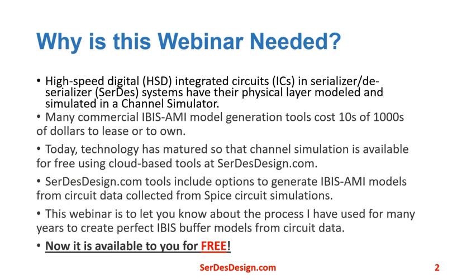Why is this webinar needed? Well, high-speed digital integrated circuits and serializer-deserializer systems have their physical layer modeled and simulated in a channel simulator. Channel simulators are designed to use IBIS-AMI models that are based on the IBIS specification. Many commercial IBIS-AMI model generation tools cost tens of thousands of dollars to lease or to own.